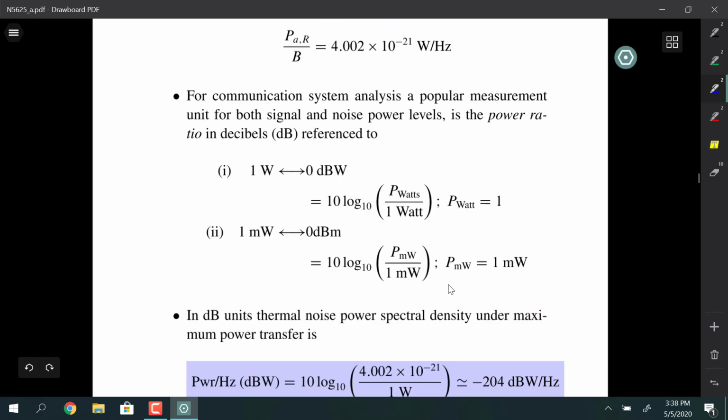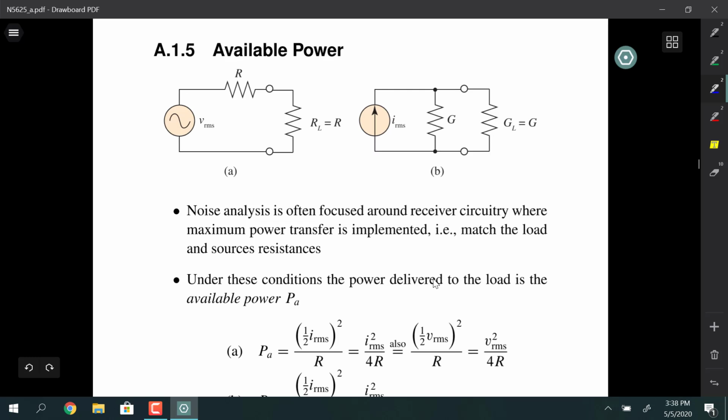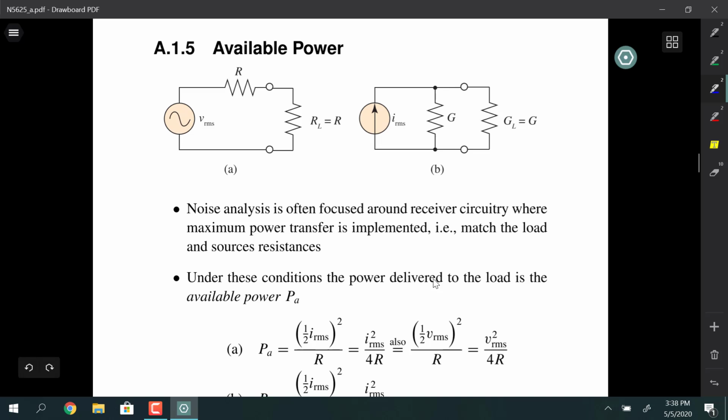So at any rate, to get to that domain, we first have to review how RF circuits are generally configured. An RF circuit is something that involves transmission line theory. But at the circuit level, it starts off by saying that you've got a source with a source resistance, and then a load at the other end that has the load resistance. Collapsing that down to a simple circuit model, we'll have a source resistance R. This is typically 50 ohms in most RF environments, but if it's cable TV, it's 75 ohms. And then at the receiving end of the system, you've got a load resistor, and generally you have that matched for maximum power transfer, something you learn about in circuits. So generally this is 50 ohms.